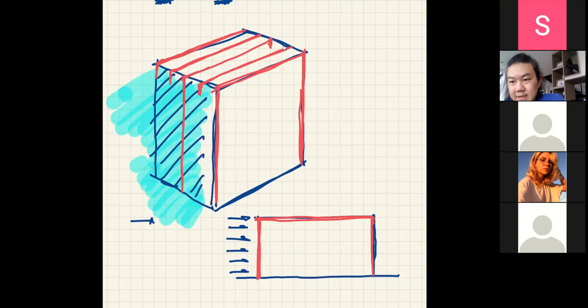And so in the same manner as you have had before, the width that each frame will be responsible for, we call it the tributary width, right? It is going to be half the distance between each frame. So that becomes the tributary width. If you decide to have, say in this picture, 5 frames.